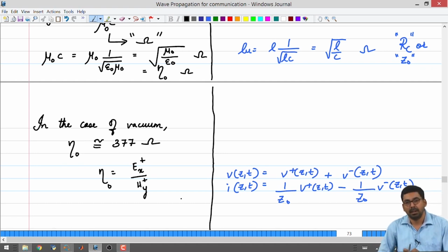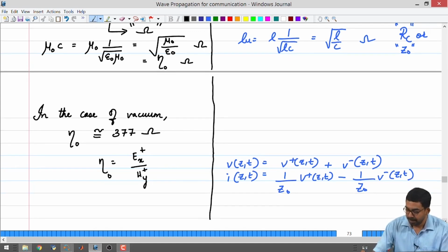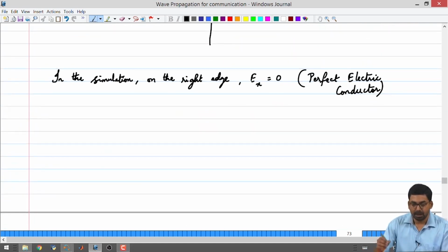So, this is another reason why we try to avoid using actual values in vacuum. You just deal with relative permittivity and relative permeability, and at the end you make an analysis: with vacuum it is this, with this material the velocity is this, so the characteristic impedance of this material has to be so much. This is the kind of analysis that you make with comparison. The other thing that we can look at, which we have not looked at in the case of transmission lines, is the effect of epsilon r and mu r and some conclusions that we can draw from them.